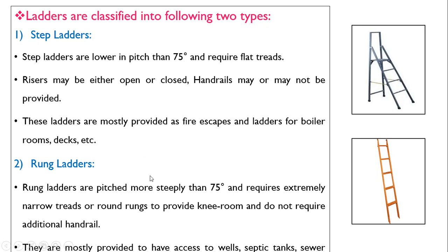What are rung ladders? Rung ladders are provided more steeply than 75 degrees. In case of rung ladders, they can be provided for a slope of more than 75 degree and require extremely narrow treads. Treads are very narrow, maybe of rounded members, maybe of flat members.